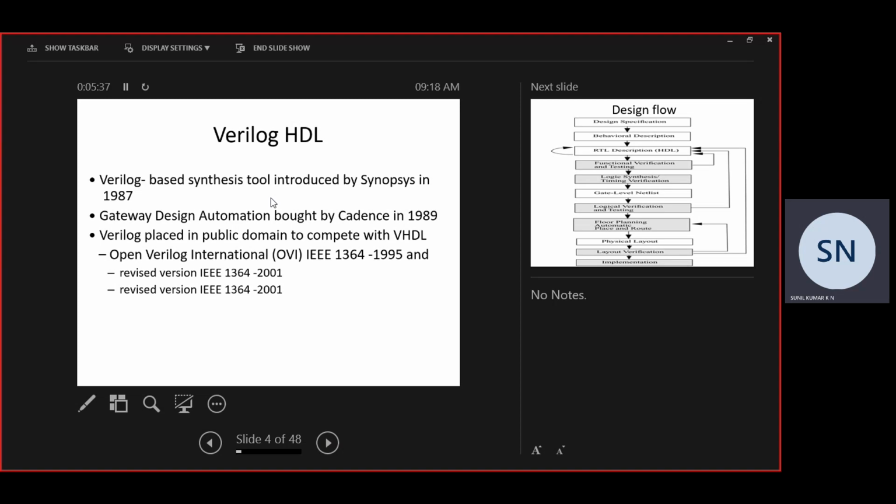In the big circuits, how can we efficiently route between the number of transistors, because all the circuits require a power supply. So that power supply is also very important, along with the clock. Clock is required for any operation, because if the clock is not synchronized with the circuits inside, we will not be able to get the proper output. So we need efficient placement, floor planning, routing, and then after routing we need to check how much power consumption it is going to take.